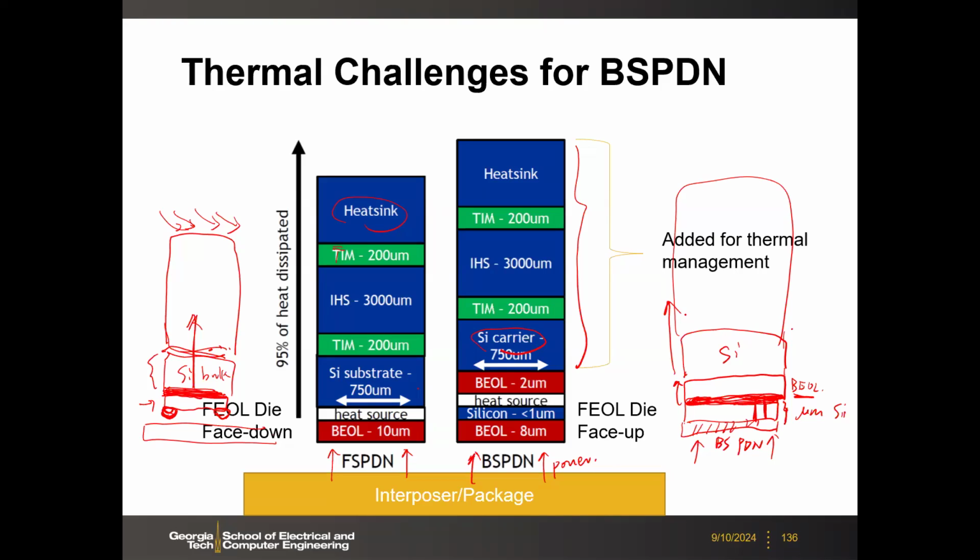How do they get? Okay, so still some TSVs. For the I/O, you still need to go through them. Let's say you have some TSVs for the power, some TSVs for the I/O. But those are not many, right? Your I/O pins, tens to hundreds of I/O pins, that's it, right? And then the routing is for their internal connections, the signal or clock or whatever. Those are generated internally, on chip. Okay.